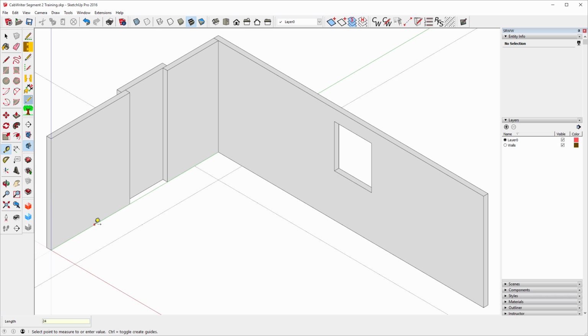The upper cabinets start 54 inches up. Basically what that is a countertop height of 36 inches plus 18 inches for the beginning of the uppers. They are 13 inches deep, so I want to bring this line out 13 inches. I'll do the same over here. And if I did it correctly, I'll have an intersection right there.